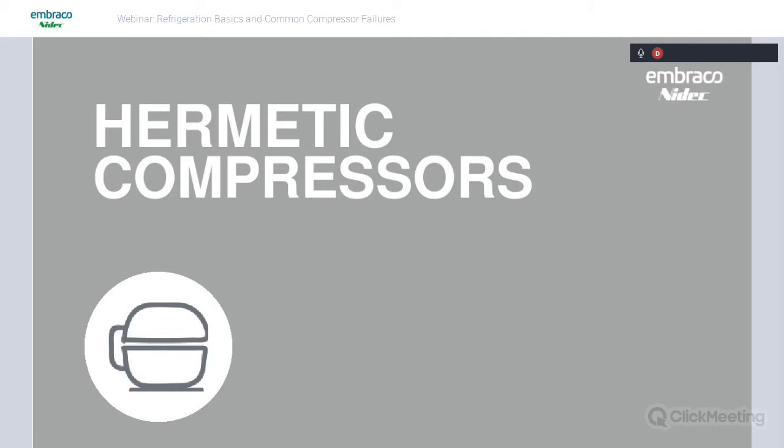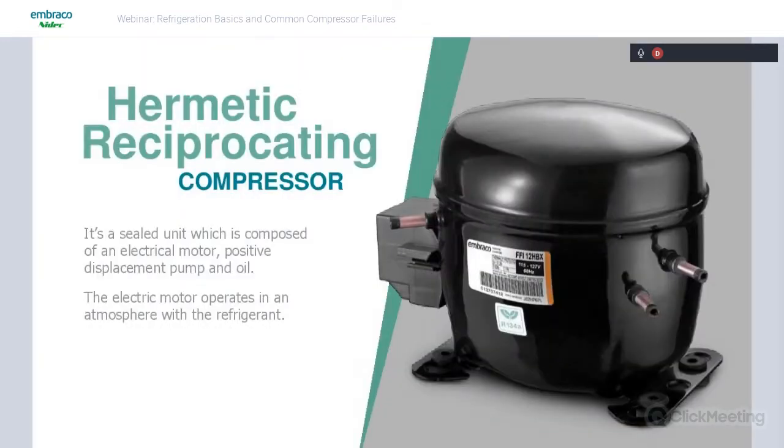So moving on to hermetic compressors. What is a hermetic compressor? It's basically just a sealed unit, which is composed of an electrical motor, a positive displacement pump, and the oil. And the electric motor also operates in the same atmosphere as the refrigerant. Suction gas is usually used to cool the motor, along with air drawn across the shell by the condenser fan. So basically, these are sealed. You cannot open them up for service.